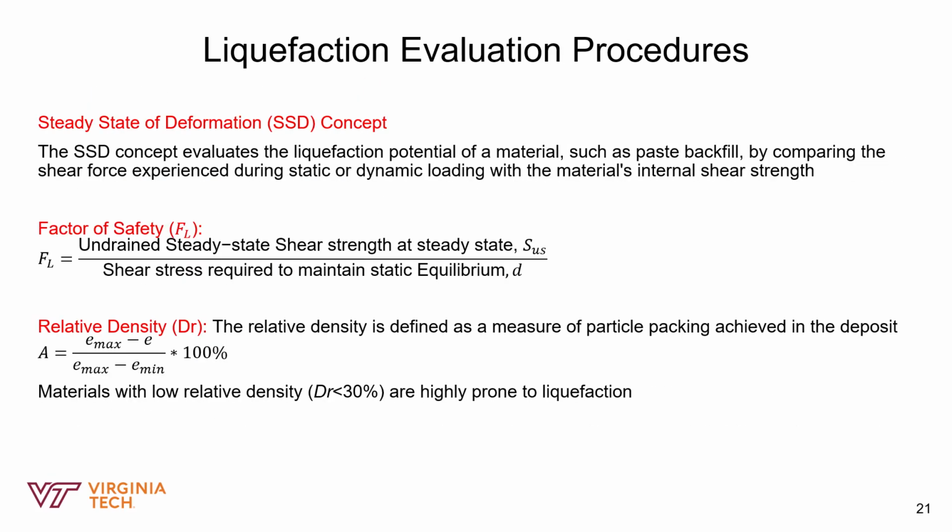This slide talks about liquefaction evaluation procedures, and this brings us to a concept called the steady state of deformation. That's the SSD concept, and this SSD concept is the primary framework that is used to evaluate liquefaction risk. It performs a stability analysis by comparing the shear force exerted on the material against the minimum strength the material can sustain internally. And that brings us to the factor of safety.